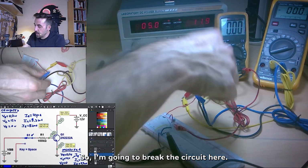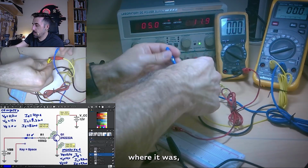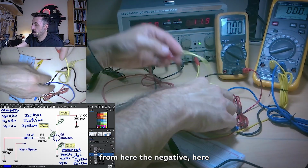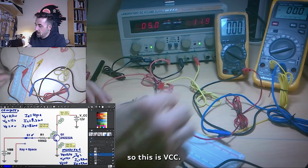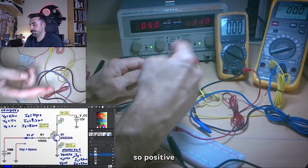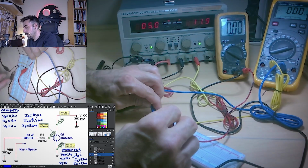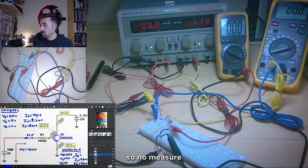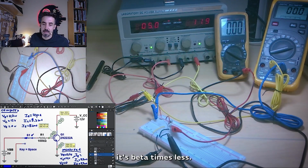So I'm going to break the circuit here. I have to disconnect my ammeter where it was, from here the negative, here the positive. That I'm going to return to the place. So this is VCC. And now the idea is the electron should pass through this ammeter, so positive here and negative in the place where that one was, with the resistor. All right, so now the current has dropped a lot. It's beta times less, so that is 200 times less.